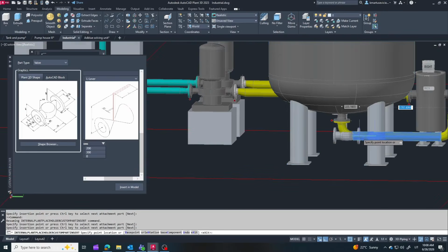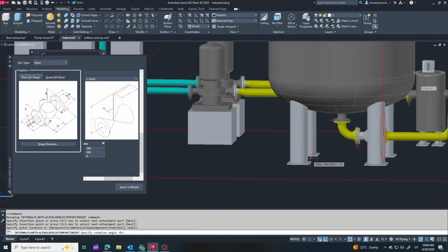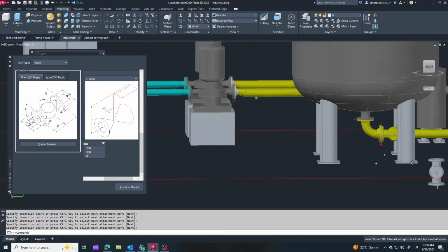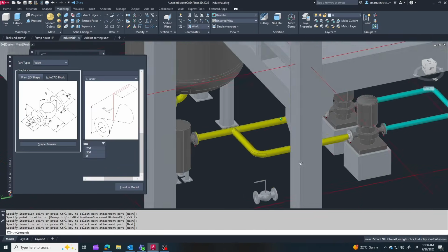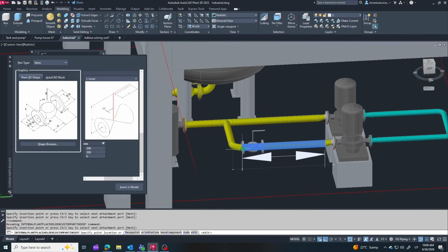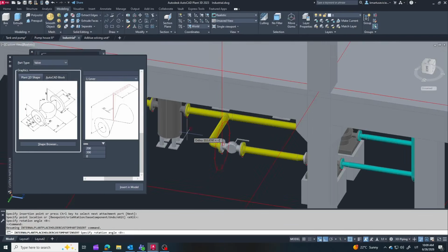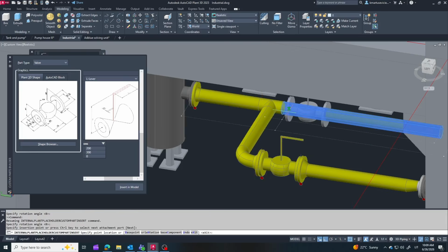Looking at the process from the beginning, every major piece of equipment should have isolation valves. The tank needs one, and each pump should have isolation valves on both the suction and discharge sides. This allows individual equipment to be isolated for maintenance without shutting down the entire system.